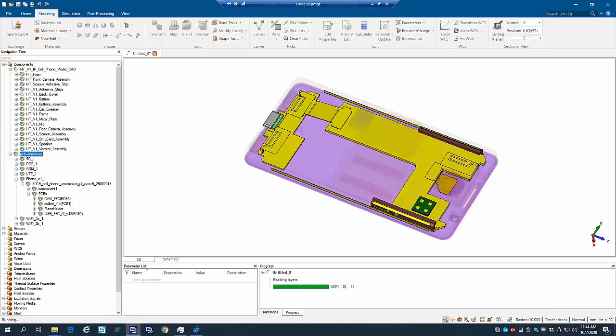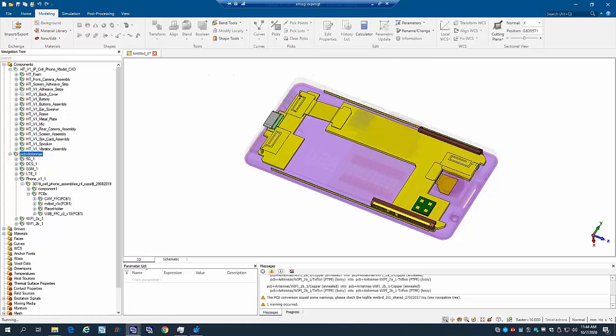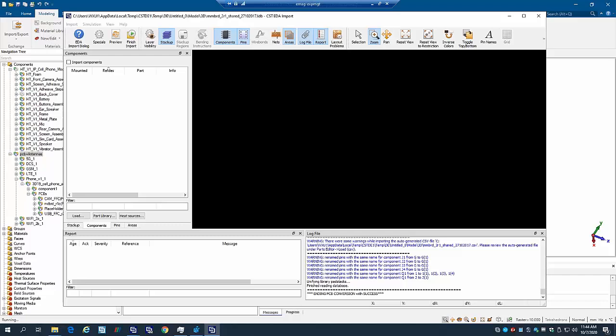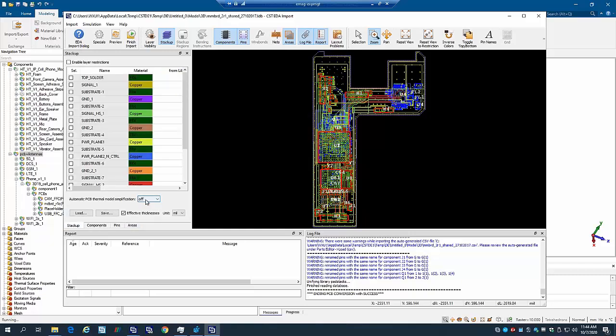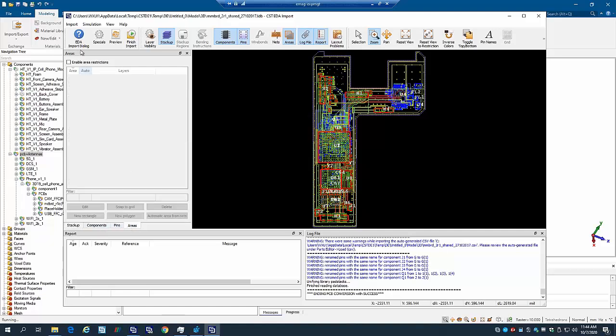So in this PCB board file, as I mentioned, you now have the option to really simplify the complicated traces with a one switch simplification here. And in 2021, there's an exciting feature I wanted to show you. You can activate the area restriction as you do with the EMAG analysis.